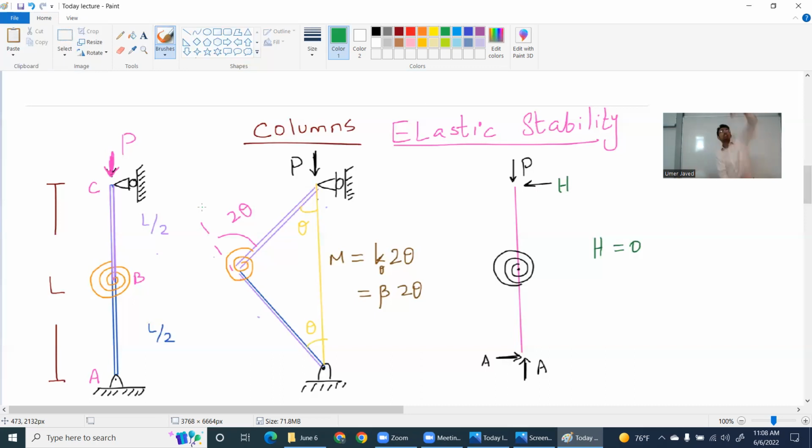So if I have a thin structure that is very long, it tends to fail by buckling. If I have a short structure that has a big diameter, it would fail under yielding. You get the point. Thin, long would fail under buckling. Very short would fail under yielding. So this is the problem in our hand.